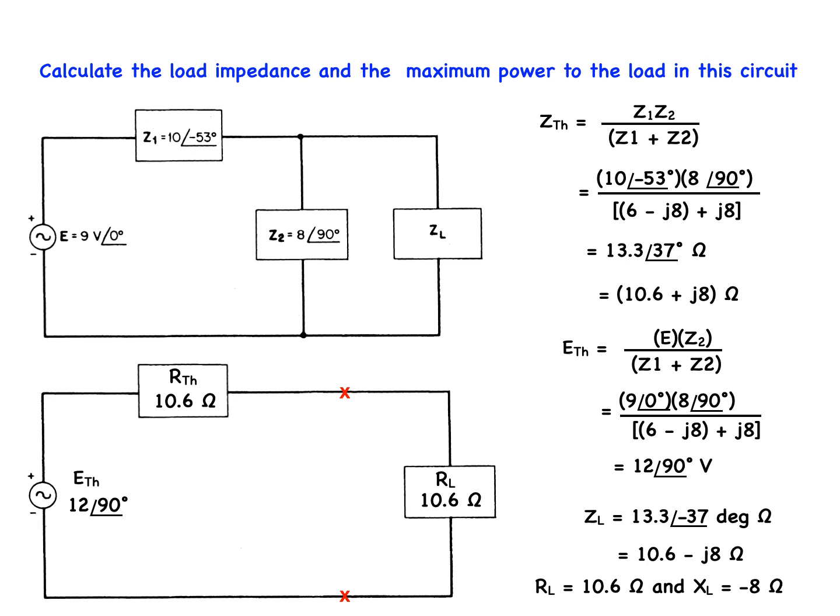Since we are looking for the real maximum power delivered to the load, we only have to consider the resistance RL part of the circuit because it is the only part of the impedance that dissipates real power. The maximum power that our supply can deliver to the circuit is given by the square of the source voltage magnitude all over the circuit resistance, E squared all over R.